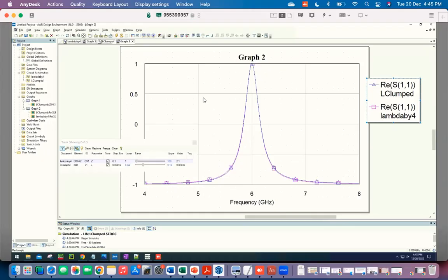you need, because this is a low impedance, means very high capacitance per unit length is what is required. And that naturally connects with the fact that I needed a large capacitance to come out of the transmission line. The reason is that the typical transmission lines we have looked at, their capacitance per unit length for reasonable dimensions is never going to be in this range.